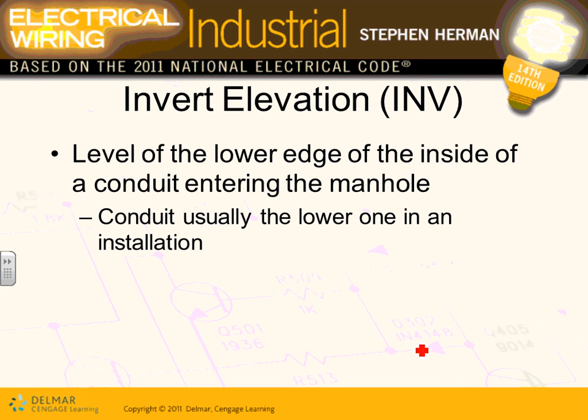Okay, so we talked about the elevation. There's something called invert elevation, guys. Kind of a weird term. When you have a manhole, look at the lower conduit inside the manhole. They go down to the bottom of that conduit.